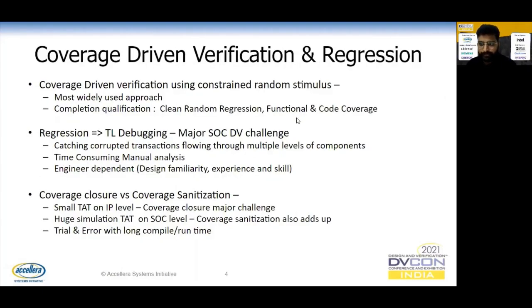For functional verification, majorly simulation is being used across our industry. Coverage-driven verification is the most widely used approach, where input stimulus is limited and filtered using constraints. In this approach, we try to excite only relevant parts of the design feature and try to see if important scenarios are getting covered by looking at the coverage score.